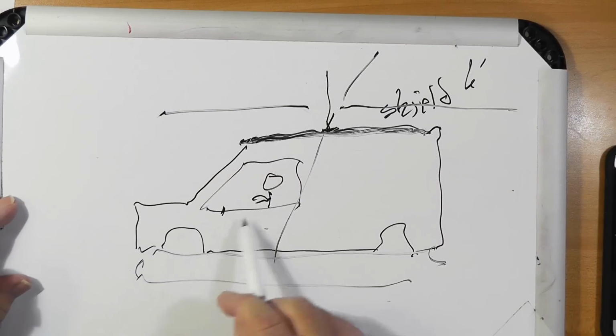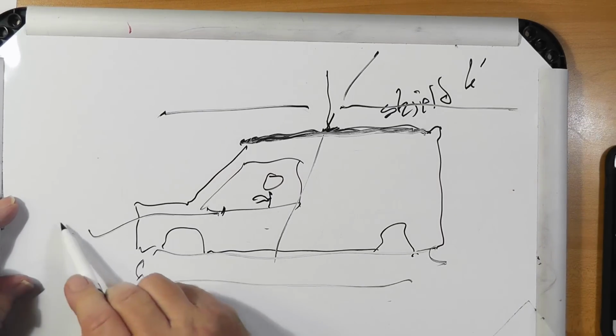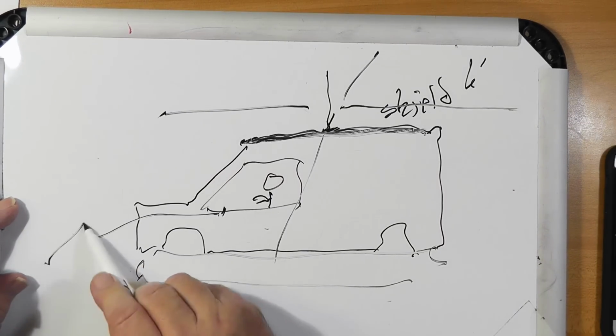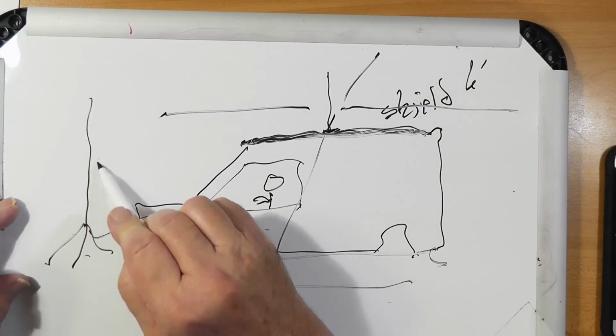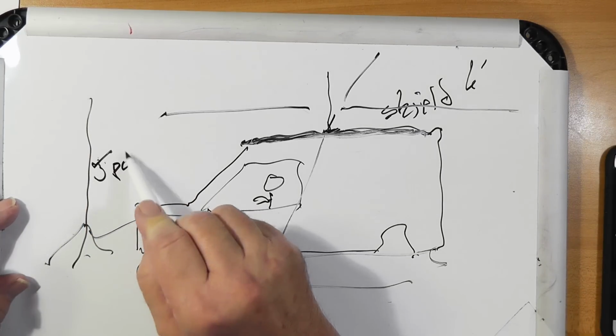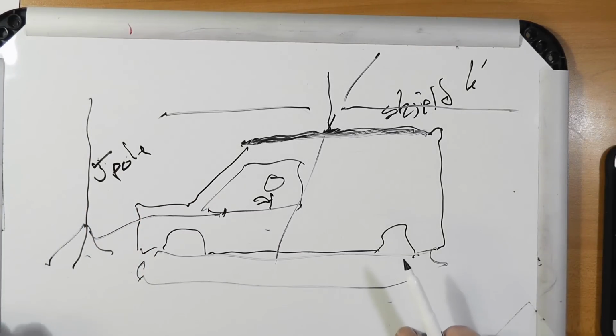Well, it's not a metal roof, and you're not going to have any luck using this as a ground plane for your antenna. So you're going to have to go to something different, like running a coax out and setting up a J-pole on a tripod. Now what does that do to you?